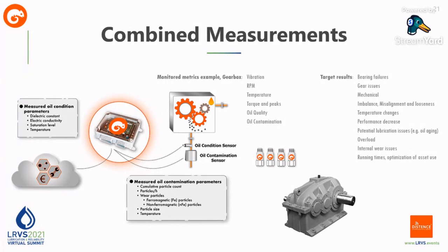In addition to the vibration monitoring, drilling down to the component level of the bearing and monitoring the gear mesh, when sudden particle bursts are detected in the lubrication system, this indicates misusage, blockages, etc. And it gives the owner a more accurate insight into possible failure, root cause, and remedy.